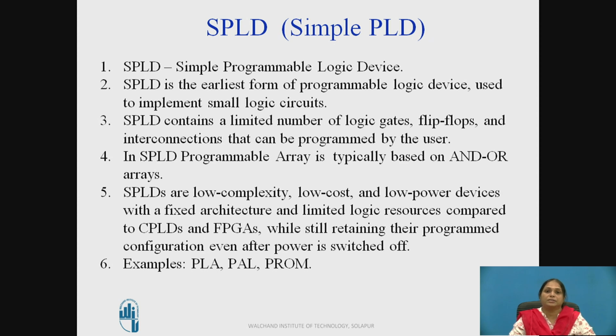First, we will discuss the simple programmable logic devices. It is the earliest form of programmable logic device used to implement small logic circuits. SPLDs contain a limited number of logic gates, flip-flops and interconnections that can be programmed by the user. In SPLDs, the programmable array is typically based on AND or OR arrays.